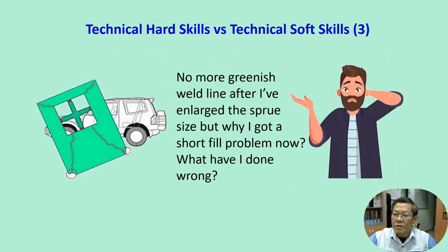In this case, the initial joint line in the molded car door panel was solved by enlarging the sprue size of the mold, but at the same time resulting in a nozzle drooling problem. When the molder tried to decrease the melt heat to fix the nozzle leaking problem, another problem happened when the part running short at the far corners. The fact is, a good product design cannot warrant a defect-free production without the support from a good mold design and proper molding method. The study of all manufacturing variables is important to solve manufacturing issues.